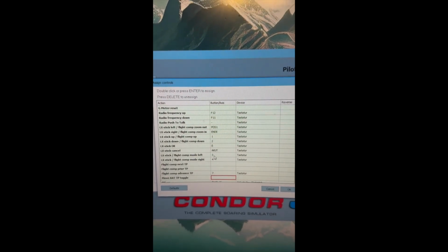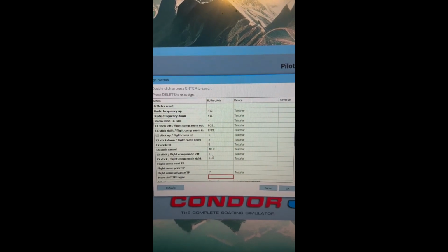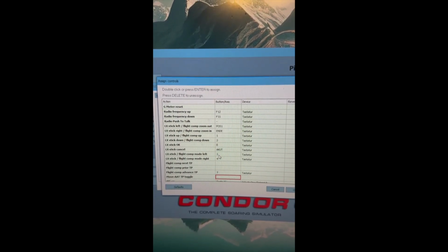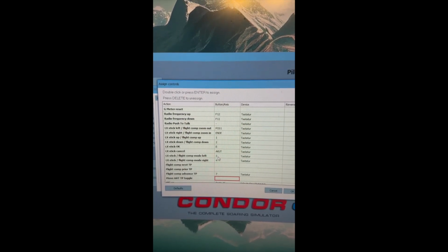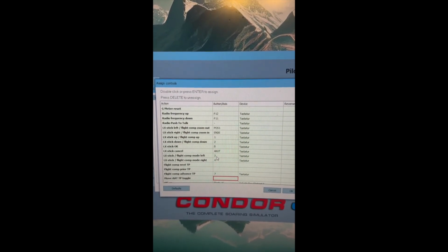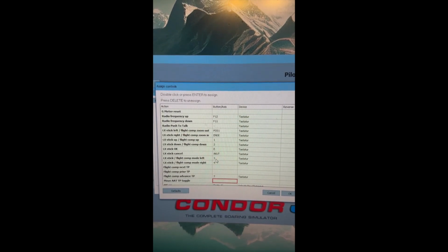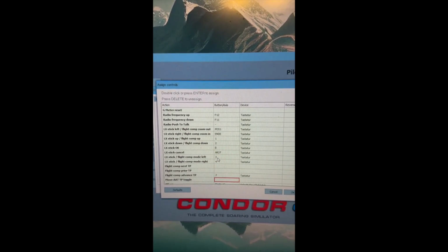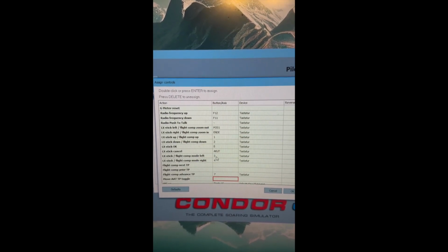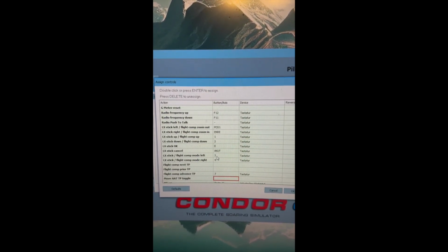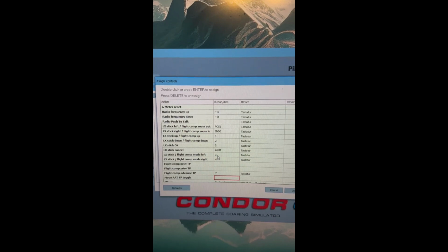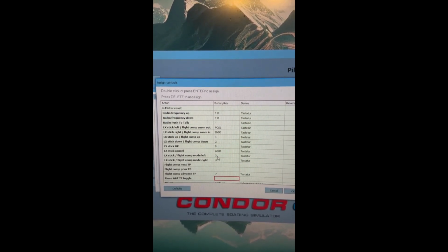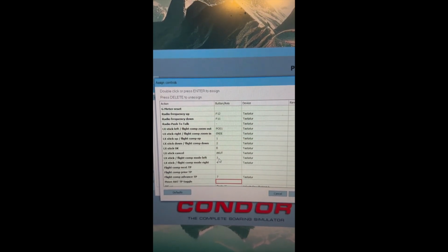And again, I really recommend to play around with those functions to get used to them by starting a flight, and play with them on the ground and in the air. For example, you can't start a task without being in the air, so this function won't be there on the ground. But to check the functions like LX stick up and down, OK, cancel, mode left and right, you can practice this on the ground, and I really recommend this.